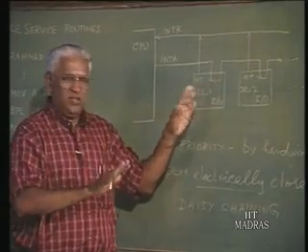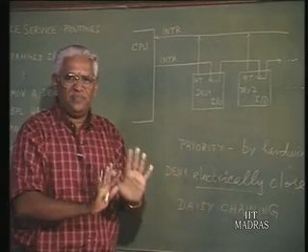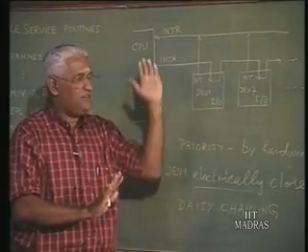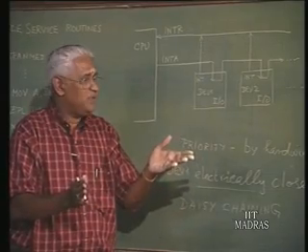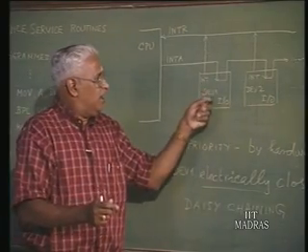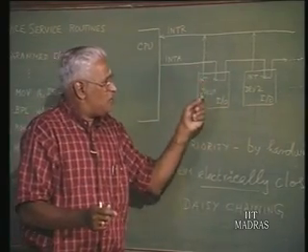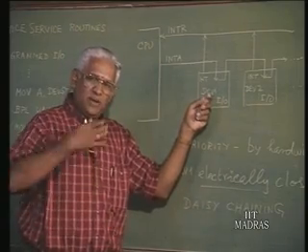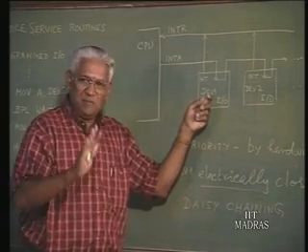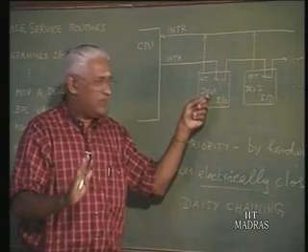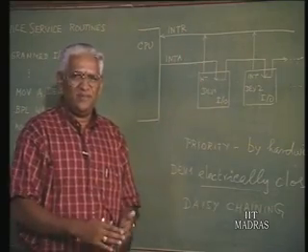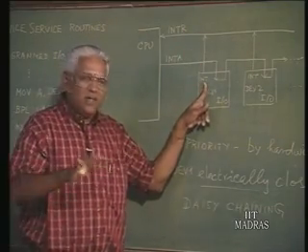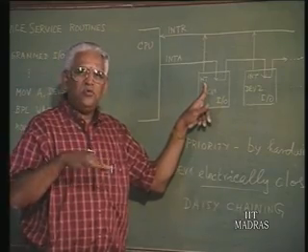It is executing a program, whether it is a main program or an interrupt service program, it is just a program. And the interrupt acknowledge has gone to device 1 and the service program has been started. So, it will be meaningful to assume that this device itself cannot interrupt itself again. So, this interrupt input would have been cleared.